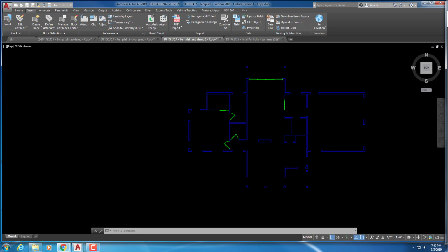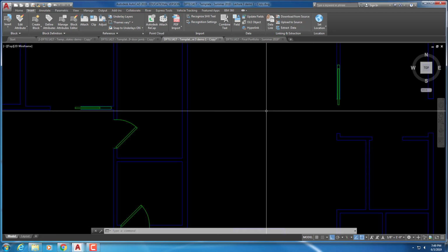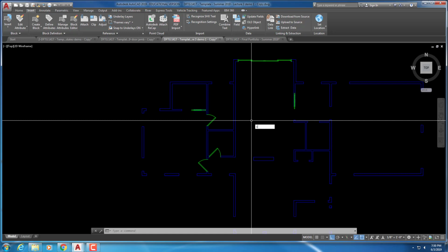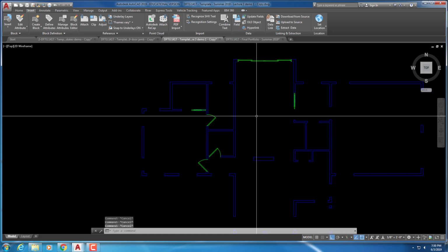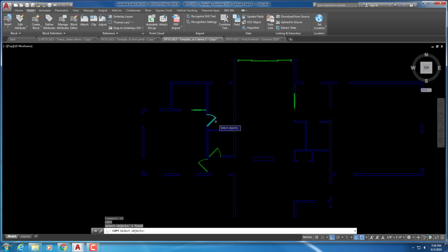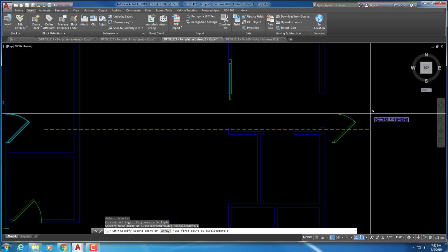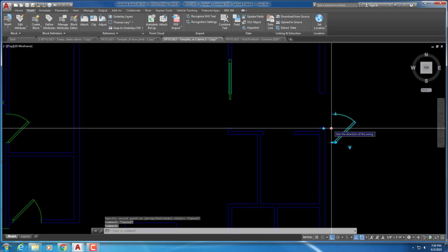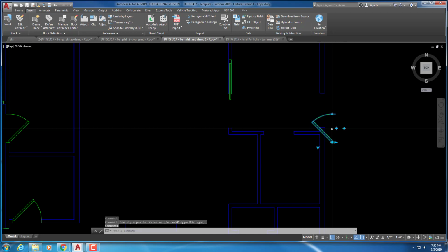The D1 is a 3-foot door, and it's in from the garage into the utility from the other side. So either copy a door or just drag one in. I think I'll just copy one of these already. Let's see. It's going to open the opposite direction, so I'll use the flip arrow, maybe.